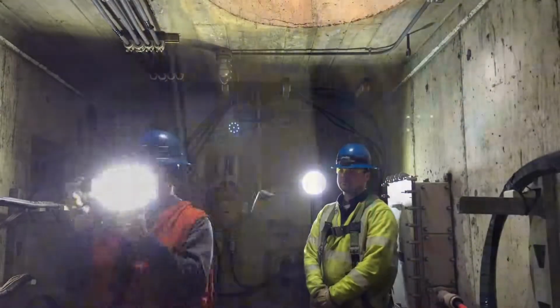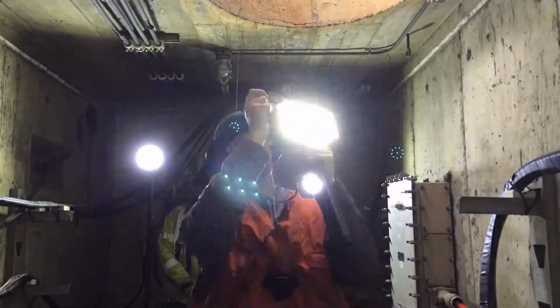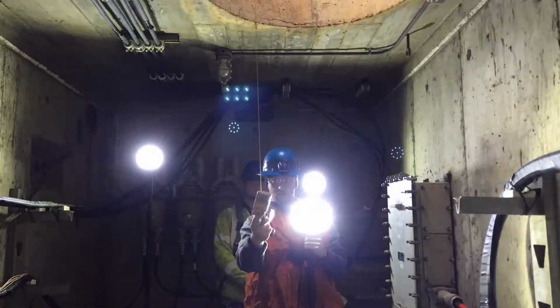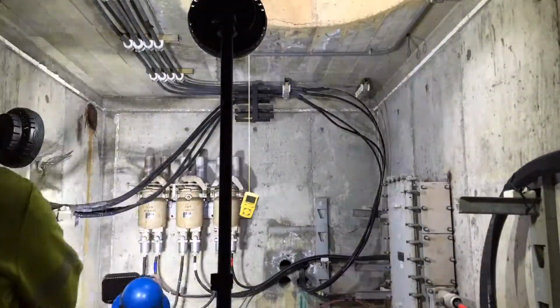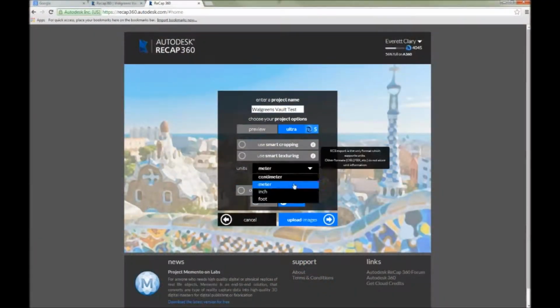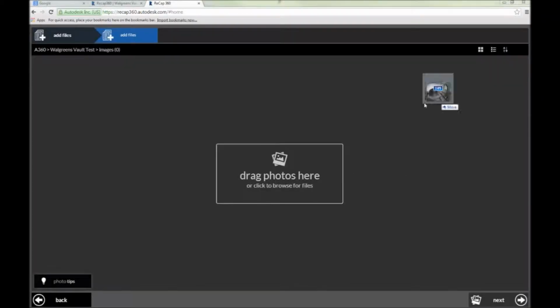We employ high-capacity lights for our cameras, as this produces the best models. Due to the nature of our equipment, we don't know if we have a successful model until after we have run the pictures through ReCap, so sometimes we must repeat this procedure. We select about half of our pictures to upload into the ReCap software.